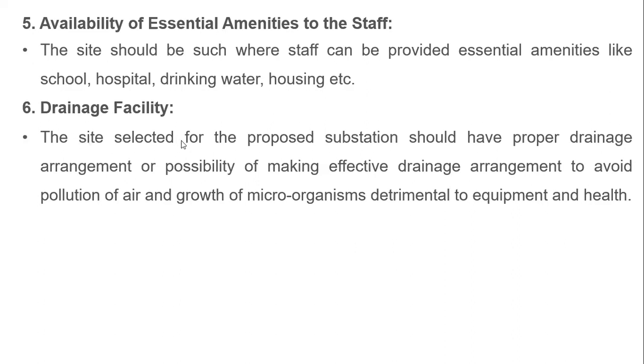Next, drainage facilities. The site selected for the proposed substation should have a proper drainage arrangement or the possibility of making effective drainage arrangements, to avoid pollution of the air and growth of microorganisms, deterioration of equipment and effects on health conditions. These are the factors to be considered for the selection or location of the substation.